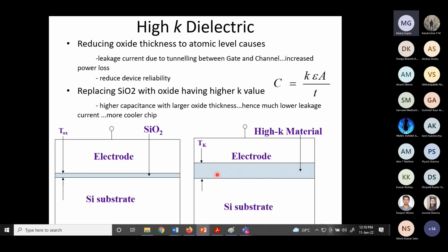And that gives silicon an extra edge over gallium arsenide or germanium. They don't have a stable oxide, you see. So if you want to make a transistor with germanium or gallium arsenide, you usually make a MESFET, metal semiconductor, rather than a MOSFET. You can't make a MOSFET because they don't have a proper oxide.